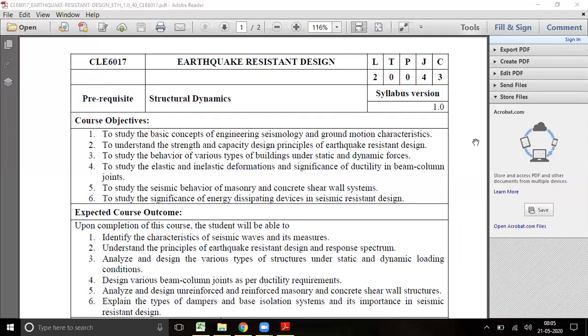These will come under non-structural components. If anything happens to the non-structural components, it won't affect the overall global behavior of your building structure, so your structure will be safe. If any partition walls or infill walls get affected, it won't affect the overall structural behavior.